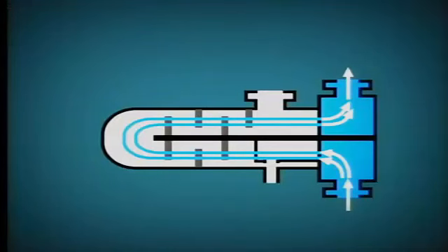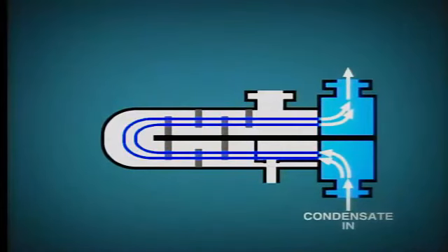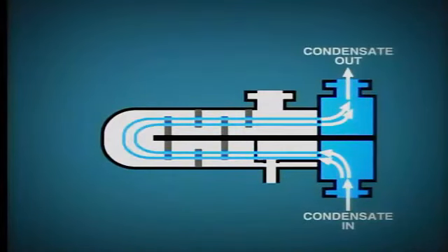This type of heater is known as a tube and shell heater. Water enters at one side of the water box and passes through U-shaped tubes to exit at the other side of the water box. The condensate is pushed through the large number of tubes, typically about 300, by the pressure on the condensate pump discharge. The tubes are supported and held in place by internal baffles.